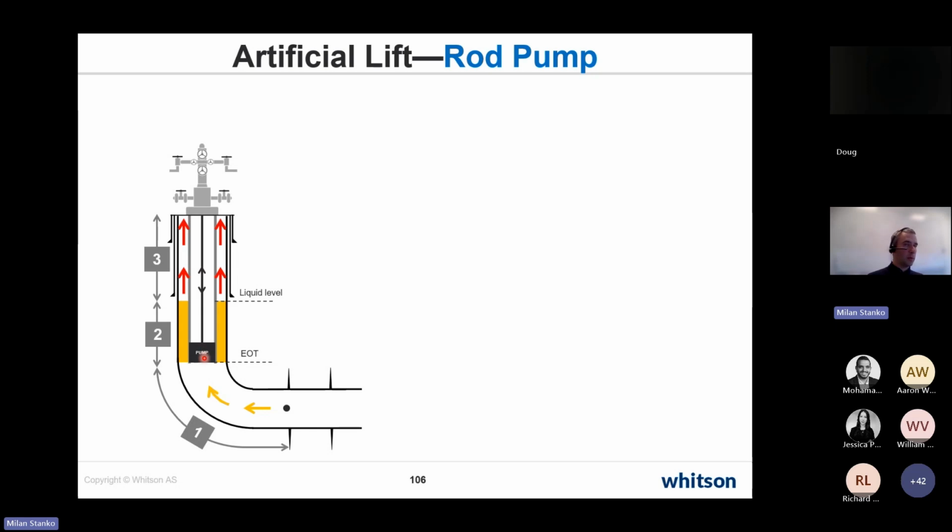So that's why the best method that Whitson found to estimate the bottom hole flowing pressure is to use the liquid level. I might have some flow of gas through the annulus, so I flow from the casing head pressure, assuming no liquids come with it. Then I reach the liquid level that I measured, maybe with some automatic gun. From there I calculate down to where the pump is located, usually the end of the tubing. Here you have some other nice figures in the manual.